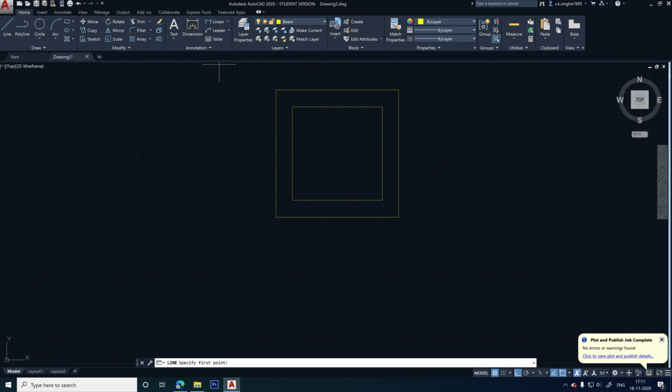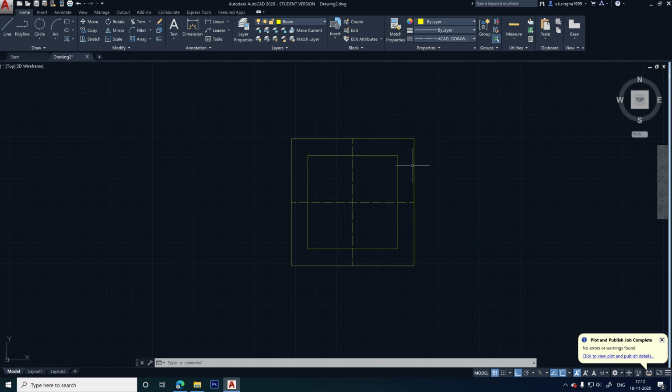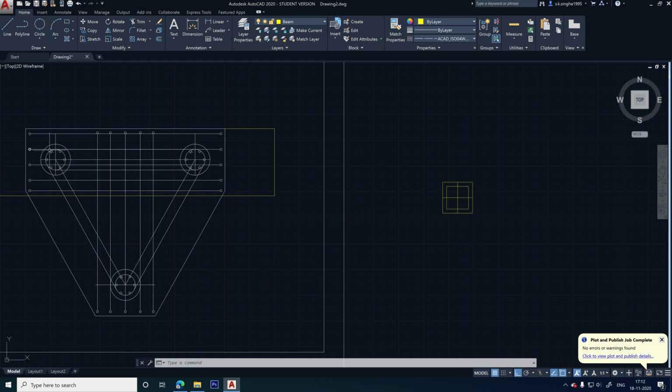Now what you need to make is the center line. So change the type of the line. Done. Now you have 1 2 3 total 8 numbers of bars in all the sides. Okay, so what you can do is, you can make one single bar, likewise we have done previously in case of the pile, and you can make the array.